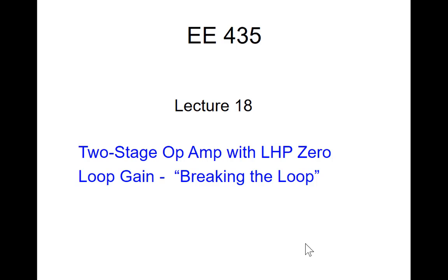And then you'll go and adjust your compensation capacitor to get the performance that you want. So maybe we can look at phase margin as something that gives us a first approximation, but since it's not related to anything that we really want, it's an artificial intermediate parameter, and we wouldn't expect that it would necessarily give us the properties of what we would want.